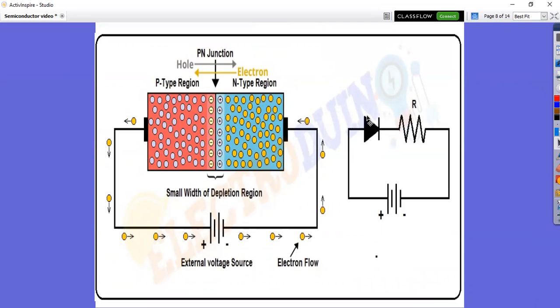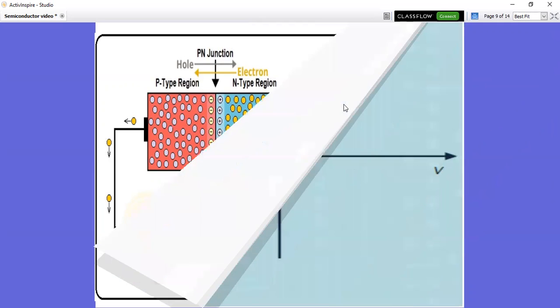And if you've ever opened up one of those power supplies, you can see 4 diodes in a ring, which forms a bridge rectifier. The diodes operate in pairs such that the current only flows in one direction through the load, and we've created a DC power supply: AC into a bridge rectifier, DC out of the bridge rectifier.